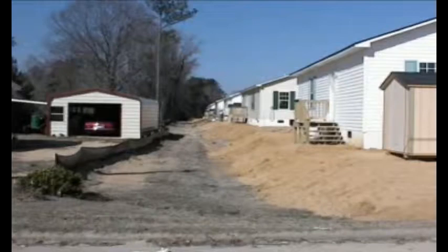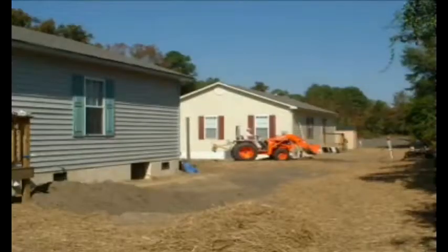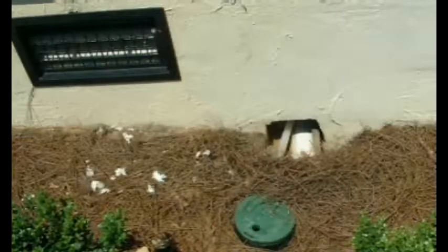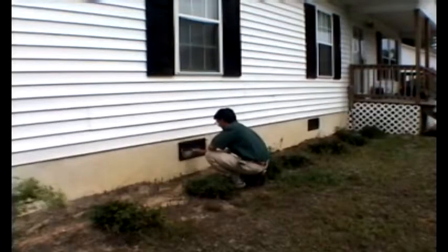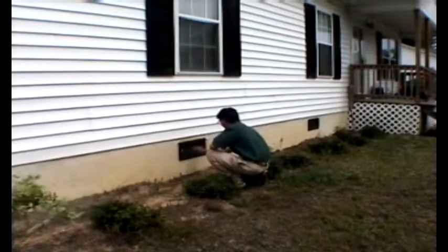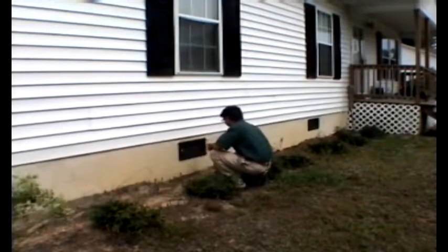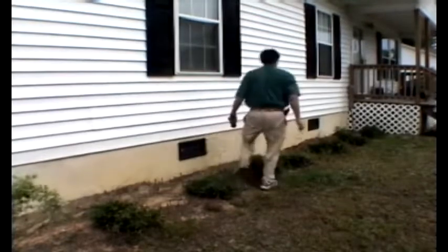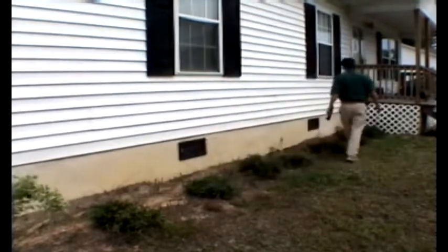During the experiment setup, all crawlspace-related moisture issues were resolved. These efforts included correcting construction, grading, and drainage problems, sealing any foundation holes that could allow water entry, and fixing plumbing leaks. The crawl spaces in these test homes average about 2 feet high, and virtually all of the wall area in the crawl space is above grade. 10 standard size 8 by 16 inch foundation vents ventilate the crawl spaces.